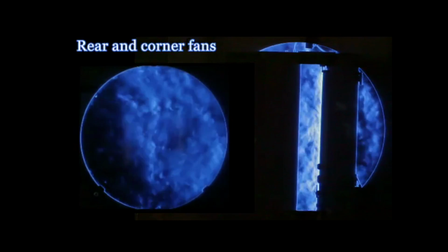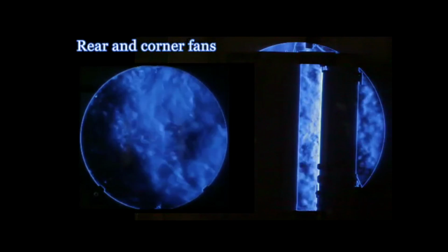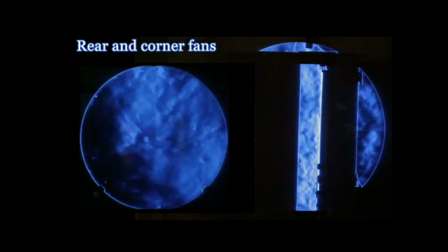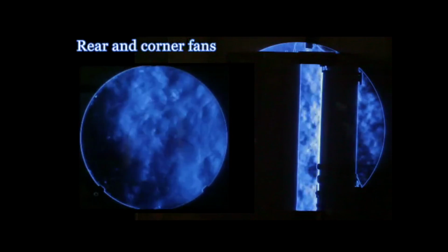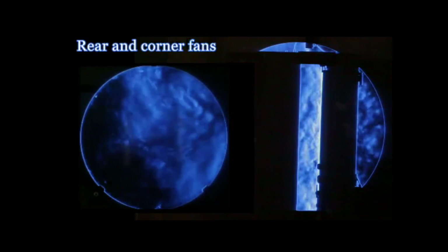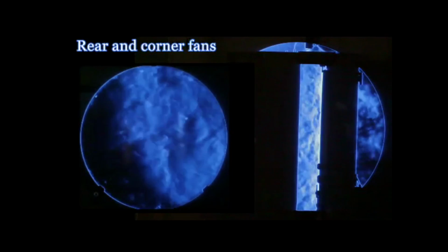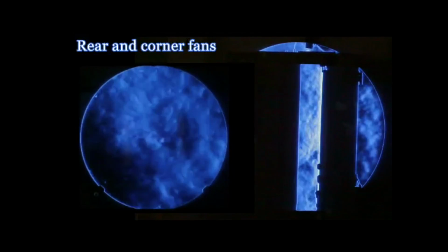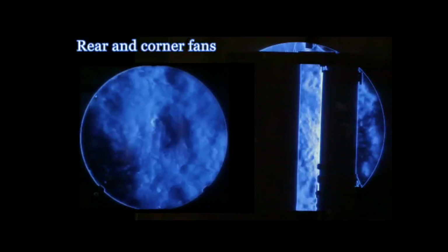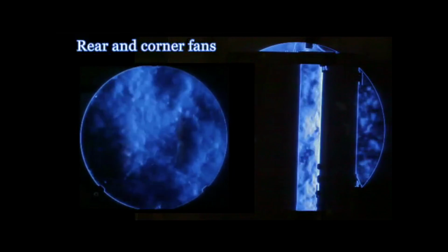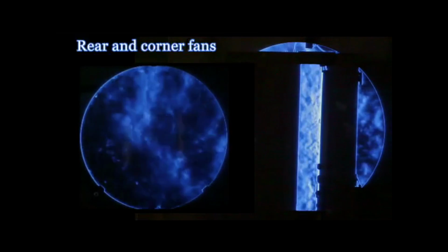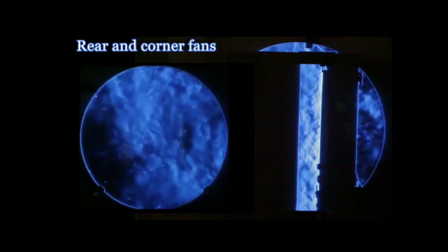All you've got to do to mount a fan, you need a little bit of vibration isolation. But if you're not running them super fast and they're good fans, it's easy to mount a fan on a bracket in the mirror box and have it directed down, because in the corners you have some space. It's not going to get into the optical path. And all these fan speed controls are so cheap now, you can control the speed of every set of fans you want to for not much money. This is the good thing about the computer industry having lots of ventilation.